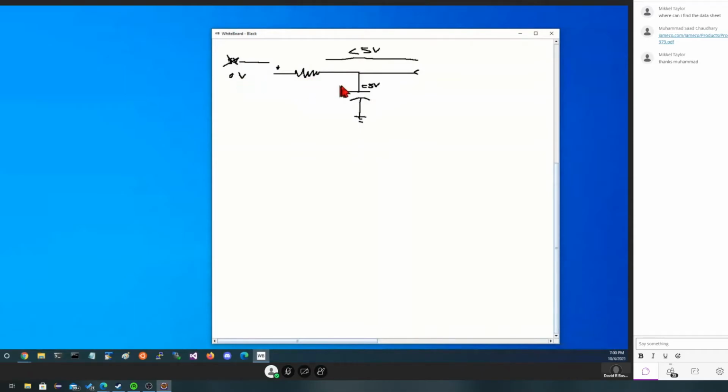So when I drop this, what I suspect will happen is this capacitor is going to slowly start losing whatever voltage it had. It could go either way. It could be stuff over here, but let's pretend like there's not for the moment. And over time, it will drain itself down to having 0 volts across it. And then I'm going to put this back to 5 volts. And we can imagine or envision that this is going to start charging. And after some amount of time, this will have 5 volts on top of it. But once this stops changing, the voltage here can't get through to ground. So it's just going to be whatever that voltage is.